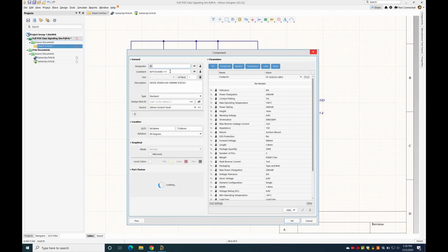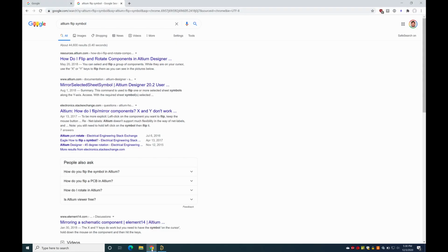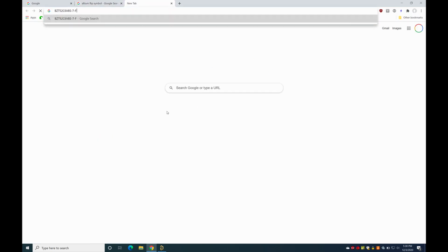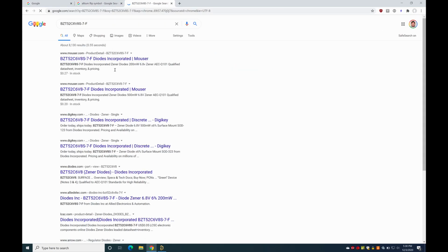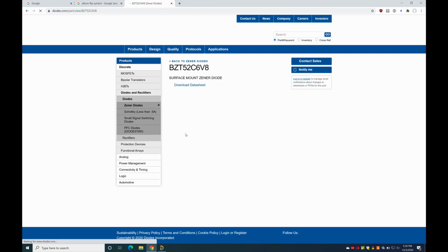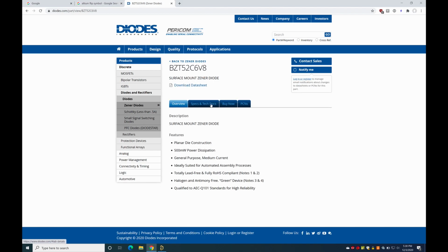Now, the last thing to do before we can actually simulate this circuit is to add simulation models to all of the components that aren't resistors and already have them. So we need to find simulation models for each of our diodes and also for those 2 transistors, or 3 depending on how you're counting. So what we'll do is kind of what you'd expect. We'll just go to the websites of those individual components and see if we can find SPICE models for each one, which we totally can. So we're just going to download all of them and then we'll go from there.